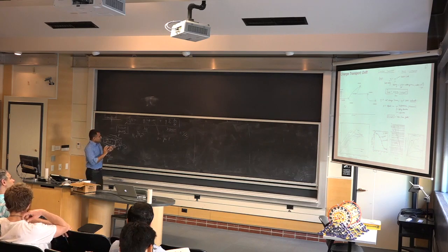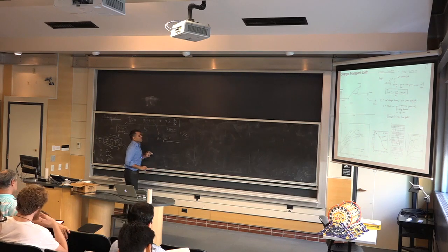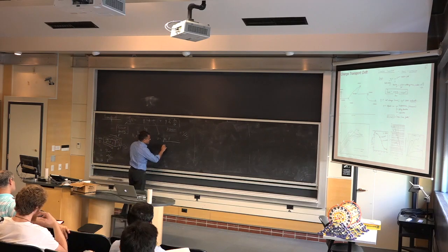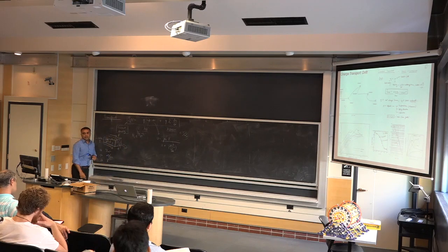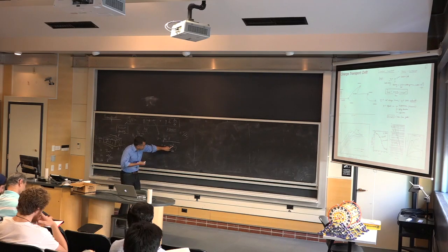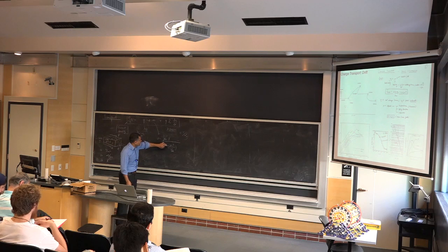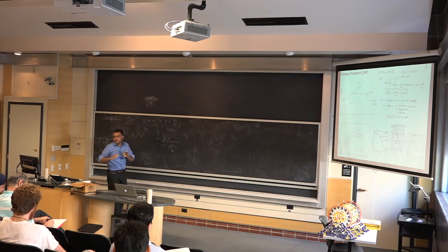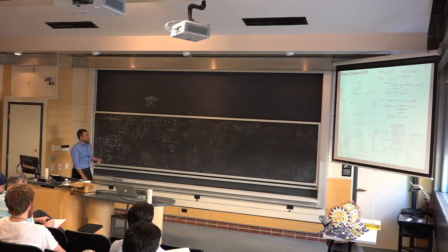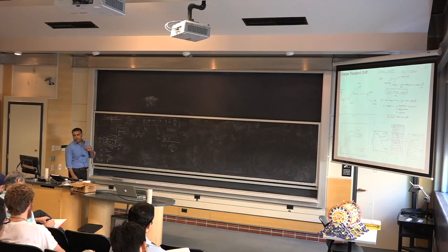The upshot of all that is that instead of the velocity being linear at all fields, we're going to take that into account with a very simple model. I'm going to say I have something else in the denominator, and I'm just going to write it like that. That captures the fact that if the field f becomes very large, you can forget the 1, and then the mu f cancel, and you get a characteristic saturation velocity. It gracefully goes from linear to saturation. So that's a model for drift velocity as a function of electric field. Most of the time we can get away with just the low field, but in some cases we have to worry about the saturation as well.